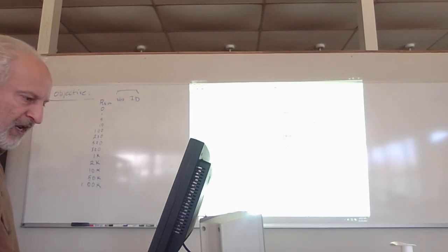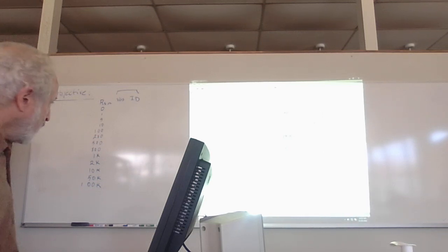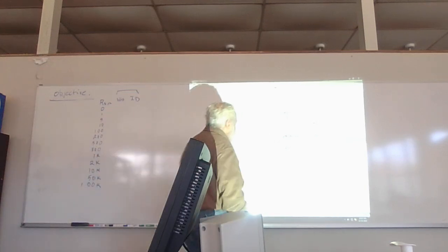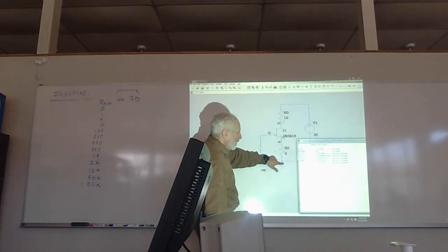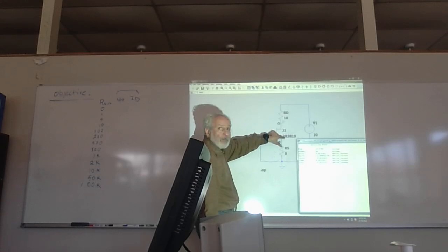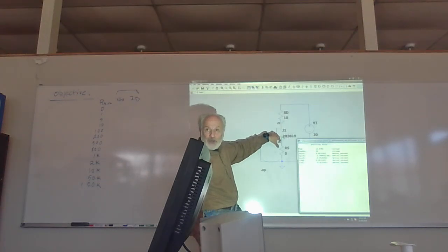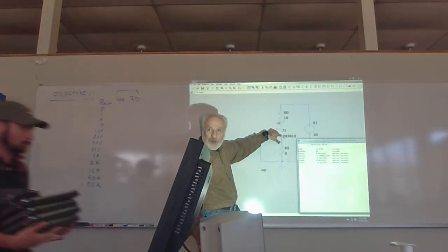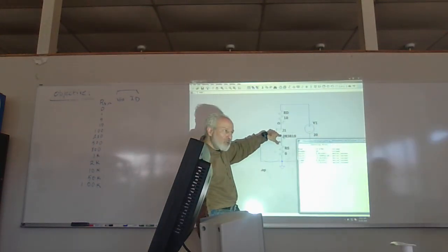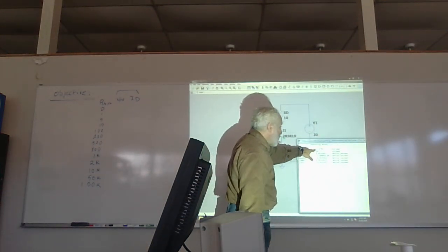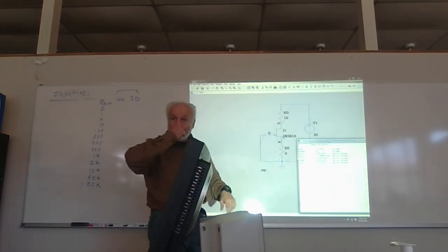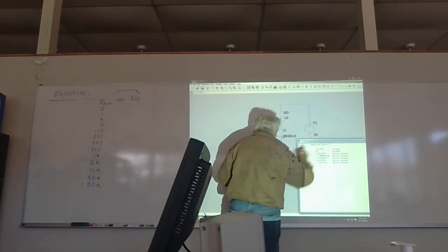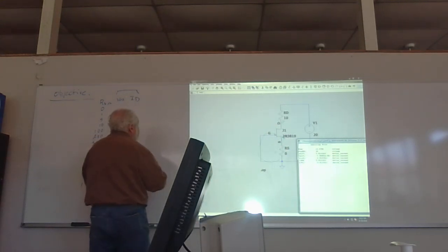So let's see what values we're getting here. VD is the voltage from here to here, and it is 19.8. What does that mean? That means I have a small voltage drop here, 0.3. Do you agree? Or 0.2. It is resistive. It's not a short. You with me so far? It has some resistance. If you want, you could track this, which I did in my lab.